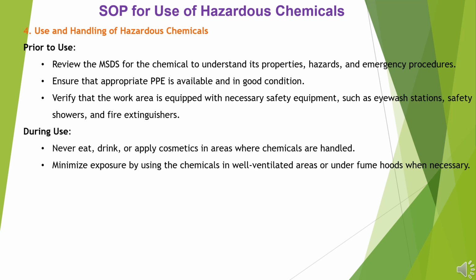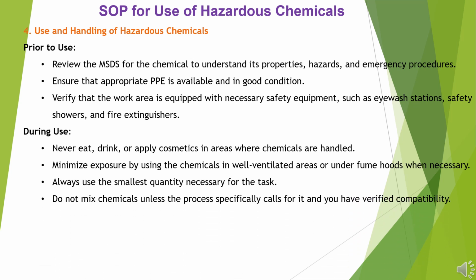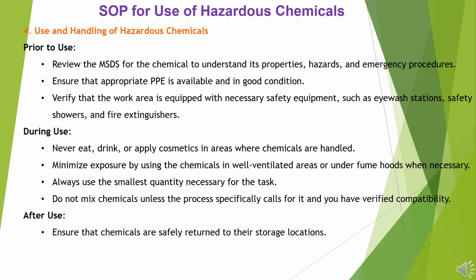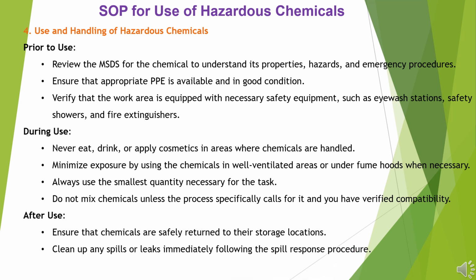Minimize exposure by using the chemicals in well-ventilated areas or under fume hoods when necessary. Always use the smallest quantity necessary for the task. Do not mix chemicals unless the process specifically calls for it and you have verified compatibility. After use, ensure that chemicals are safely returned to their storage locations. Clean up any spills or leaks immediately following the spill response procedure. Wash hands and other exposed areas after handling chemicals.